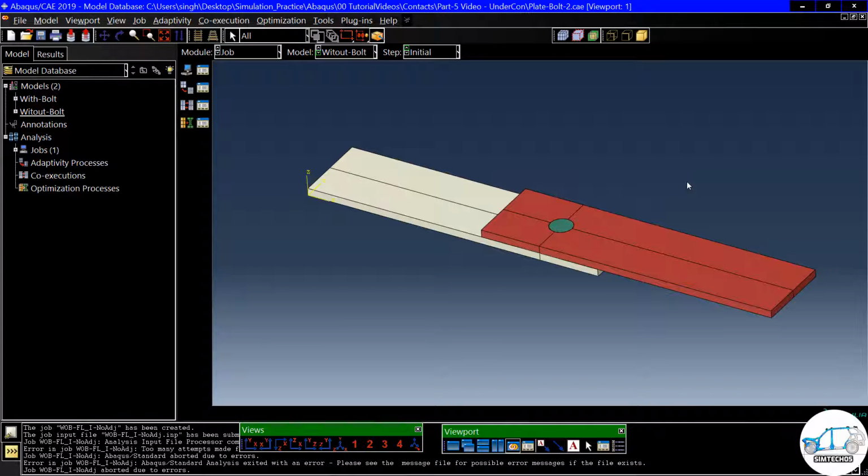Of course, in the dynamic analysis, those are allowed. Like if we solve this problem with explicit or implicit dynamic, then we have inertia effect, and due to that inertia effect, they will allow to move. But here in general static step, they don't have inertia, so nothing is going to restrict those motions.